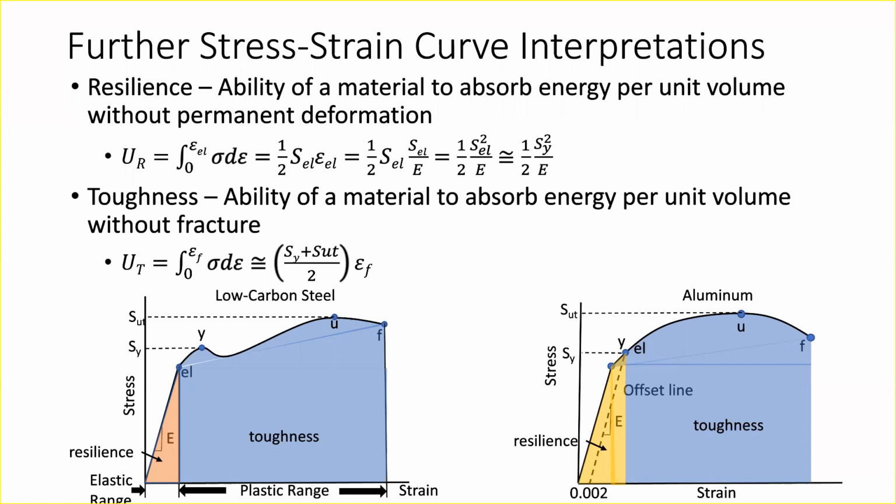If you've taken physics 1 or any calculus-based physics, you'll know that you can find the amount of energy that a spring contains just by integrating the force times the displacement, right? And the force is given by kx, so you get half kx squared for the energy. It turns out that it's no different when you go to these parts. It's really analogous. You have a continuous material and the behavior is a little more non-elastic after you go past the elastic point. But fundamentally, it's still some kind of springy elastic material, and you can predict the amount of load or energy that it can absorb by taking the integral under that curve.